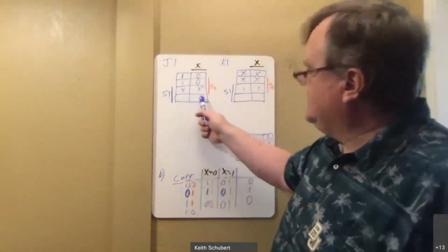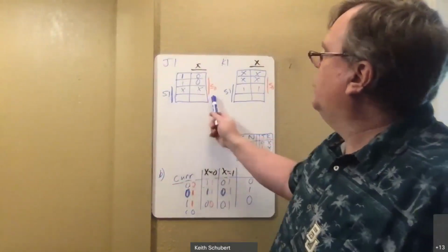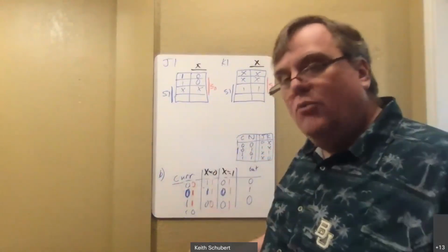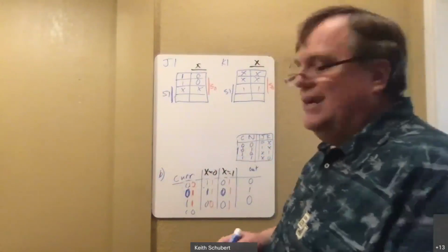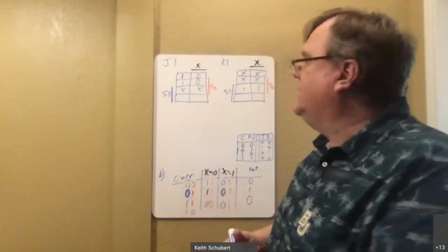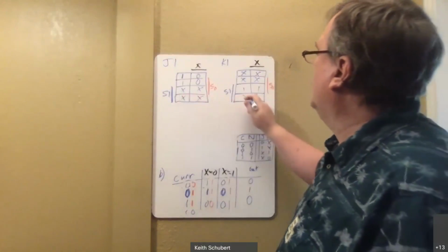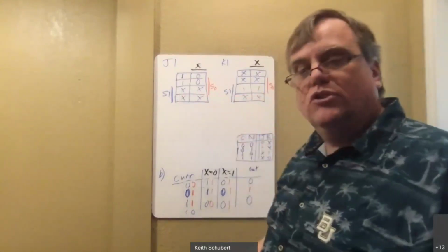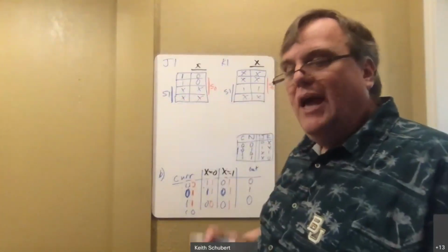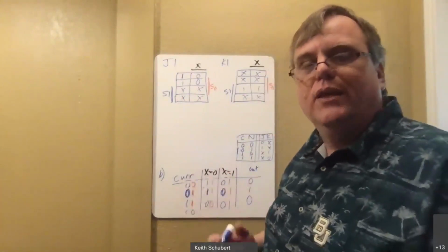Okay. The last state here is this 1-0 state, right? S1 is 1, S0 is 0, but I don't have one. And it doesn't tell me. So since it doesn't tell me, I could do a lot of things. I could make an assumption of what they are, all kinds of things like that. But I could also say, they didn't tell me, so it's all a don't care. I could care less where it goes to. This is not necessarily the most robust thing.